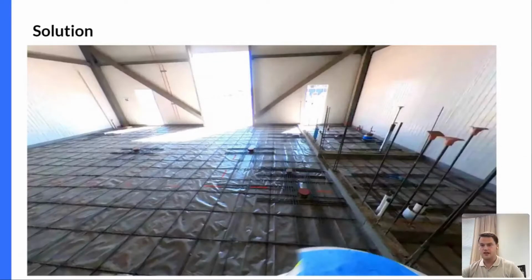Yeah, so like Nick was saying, we had quite a bit of issues with our embeds. It being a 300,000 plus square foot facility, we had over 250 embeds throughout the site. And one issue we were running into was our miscellaneous metals drawings, along with our architecturals and structurals, weren't lining up correctly. Some of them were saying 18 inches off the center of the wall, while our miscellaneous metals drawings could have said 24 inches off the wall.